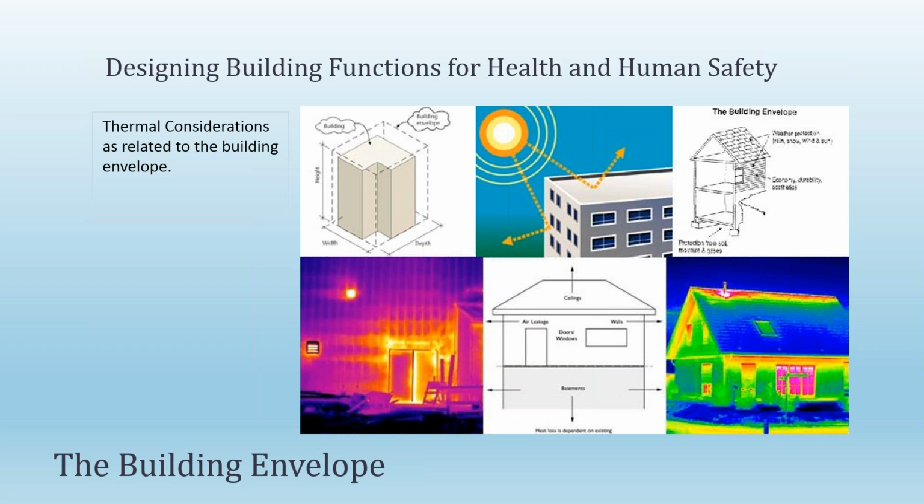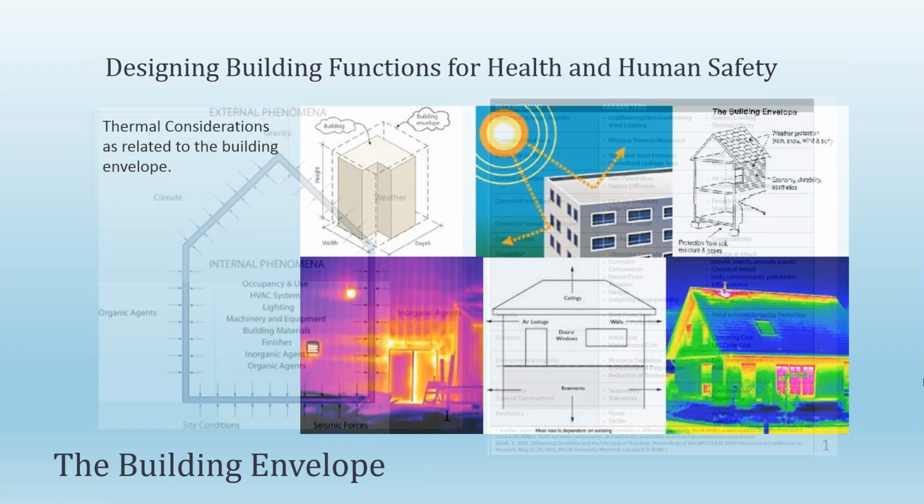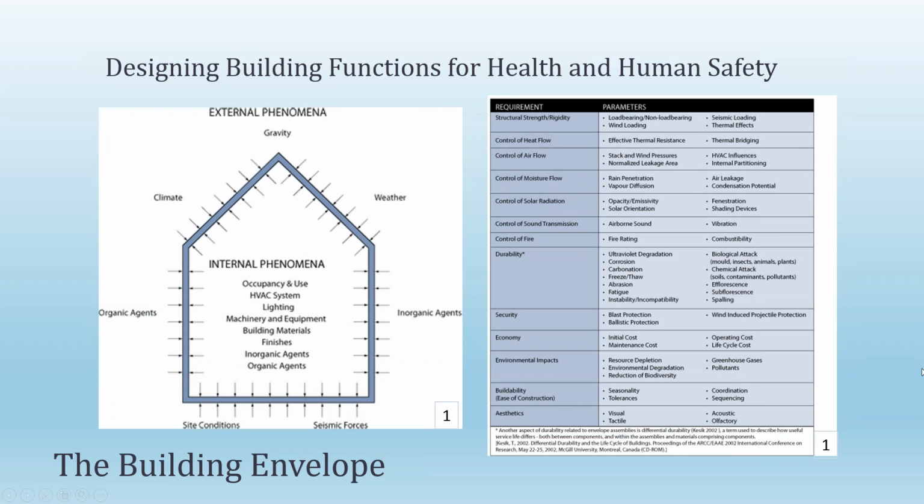Thermal mass is another important characteristic that affects thermal performance of construction. So thermal mass is different depending on location. So heavy walls, roofs, and floors have more thermal mass than light ones. Thermal mass both delays and dampens heat transfer. The time lag between peak outdoor temperature and interior heat is different. So in the desert, they have a different thermal mass to their buildings than we have in, say, places like the Midwest. So they actually have added layers of concrete to increase their thermal mass so that it stays cooler. So those are some extra things on thermal controlling.